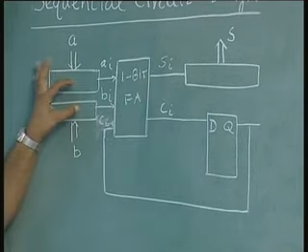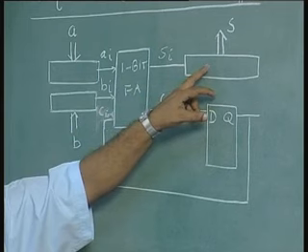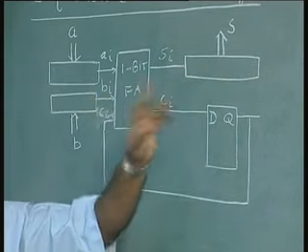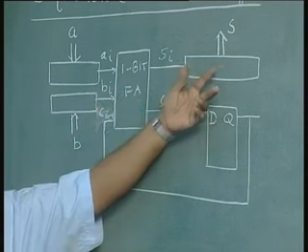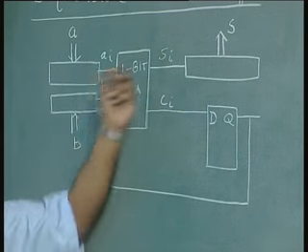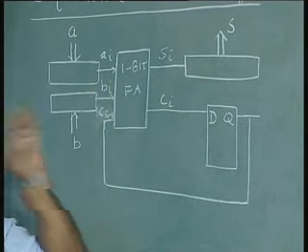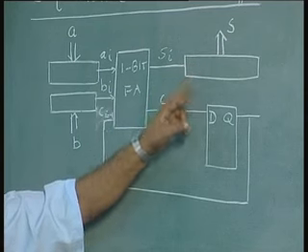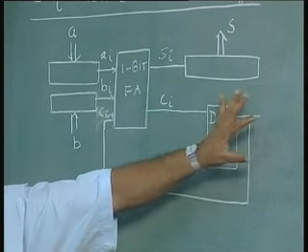For example, if I have 4 bit numbers, I may have a maximum of 5 bits. So, that means I provide 4 bit shift registers for the inputs, and I will provide a 5 bit shift register for the output. So, the last bit also will get added here, the last carry will be added here. So, we do not have to worry about the carry being separately saved and used.